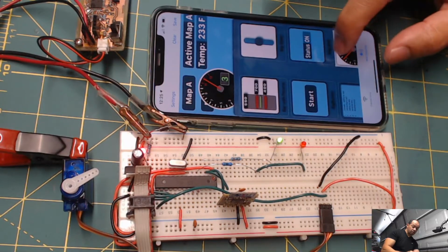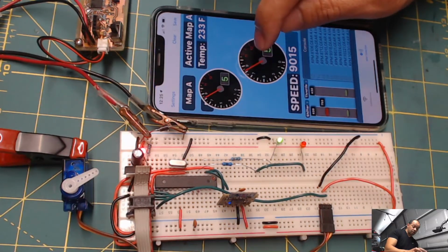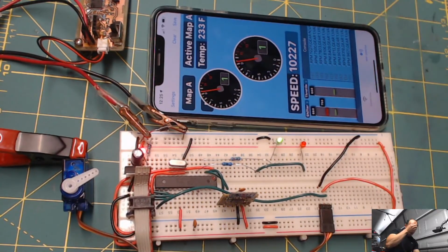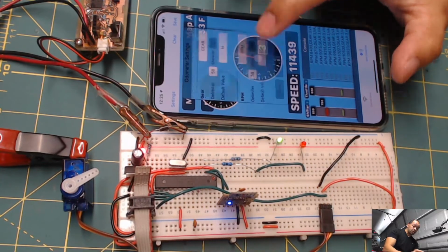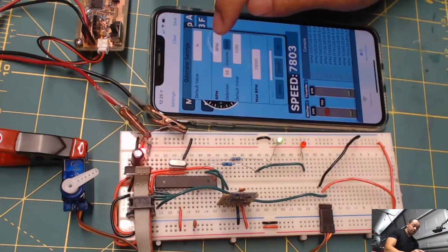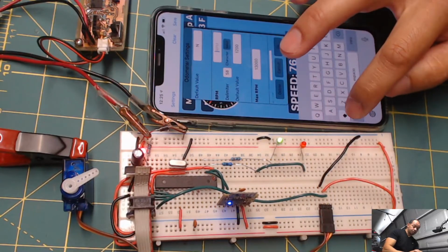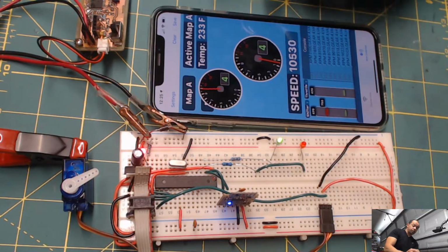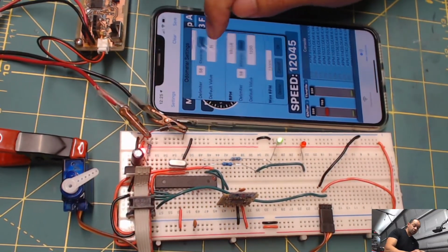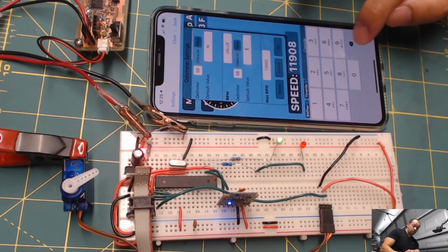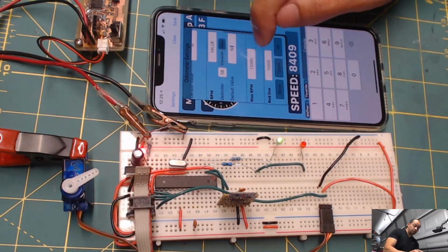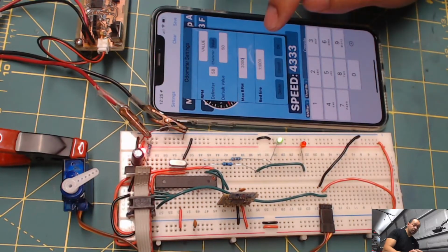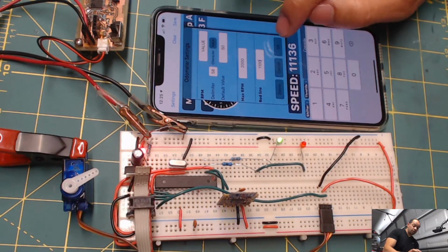Let me add another odometer, and this one is going to capture the data coming to the throttle, and I know that data is called value, so I'm just going to change the RPM to say value, and we should be able to see the needle move just a little bit. So we are going to also change the range so it becomes easier to read, or actually the needle will move a little bit more. Since we know we're getting less than 1,000, I'm going to put it at 2,000, and I'm going to put this one red at 1100.